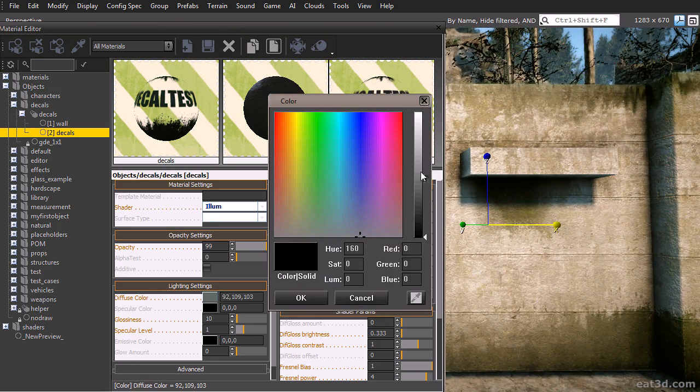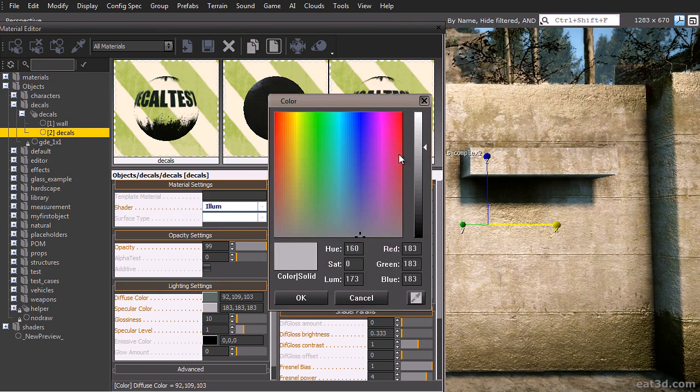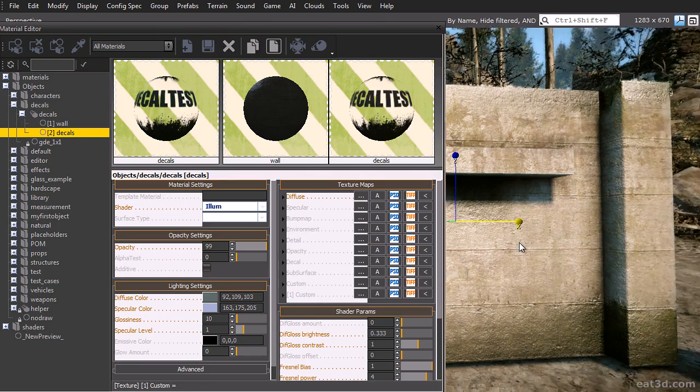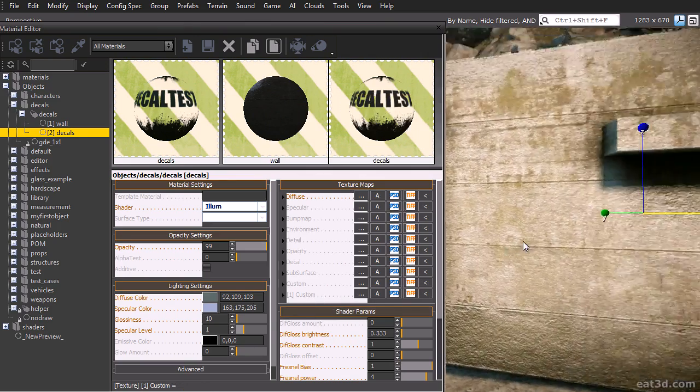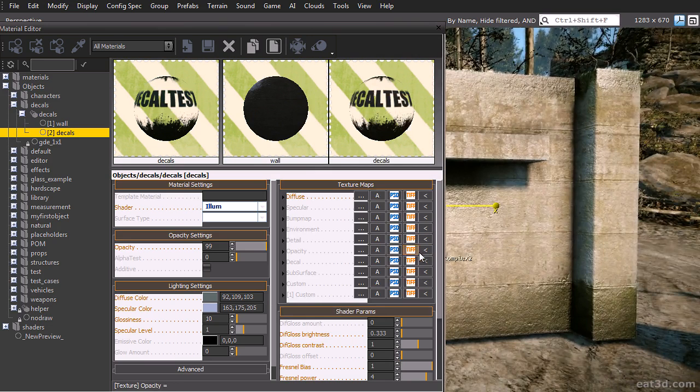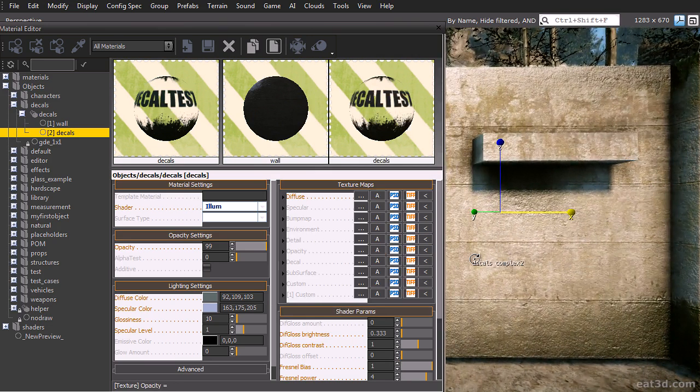You could also add a normal map allowing you to create decals with more depth, or change the specularity settings in the decal shader allowing you to create a wet look or all kinds of other cool effects. If you create your own decals, please make sure to merge them into the render mesh before the final export and also move them as close to the surface as possible.